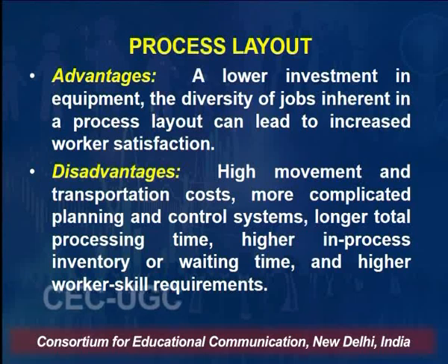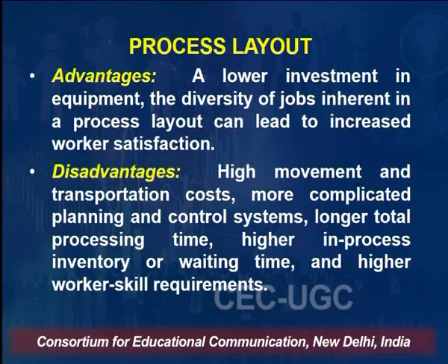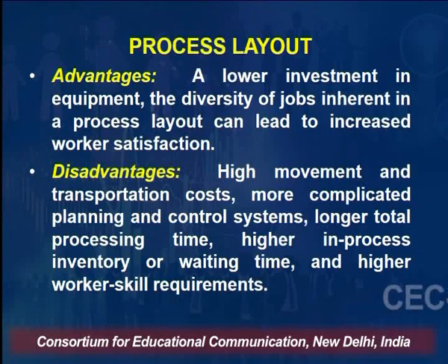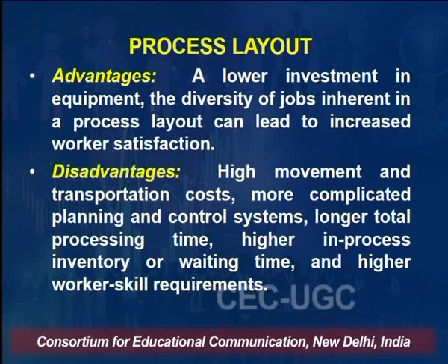So what are the advantages of a process layout? The advantages of process layout: a lower investment in equipment, and the diversity of jobs inherent in a process layout can lead to increased worker satisfaction. But the disadvantages are high movement and transportation costs, more complicated planning and control systems, longer total processing time, higher in-process inventory or waiting time, and higher worker skill requirements. So here, it's opposite to product layout.